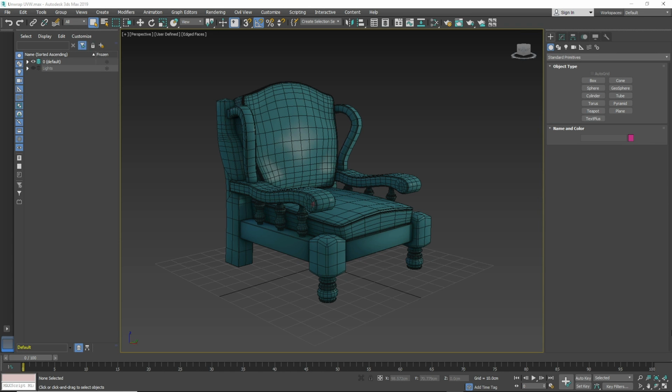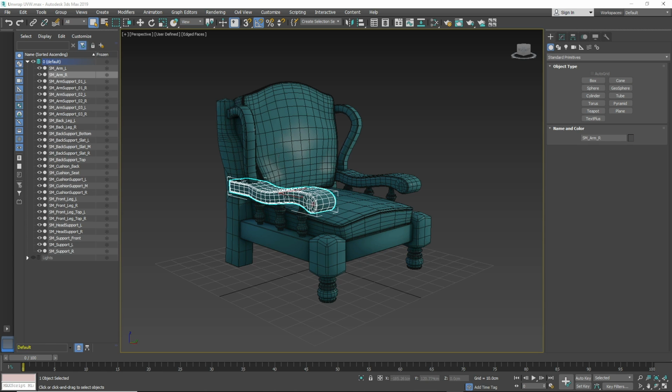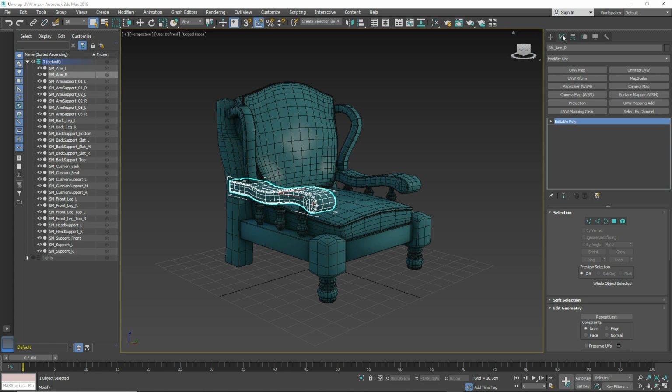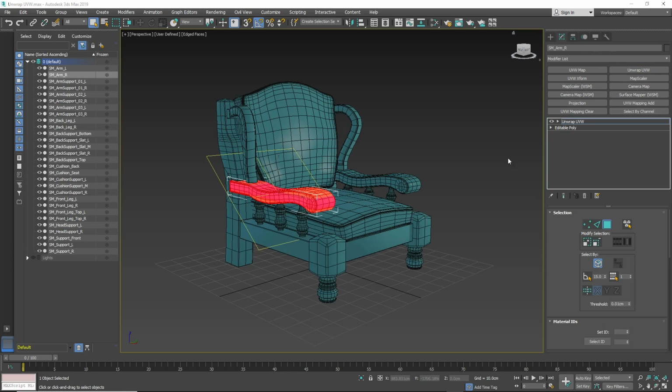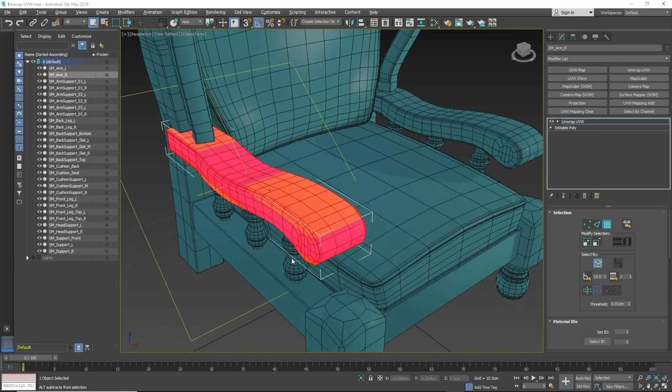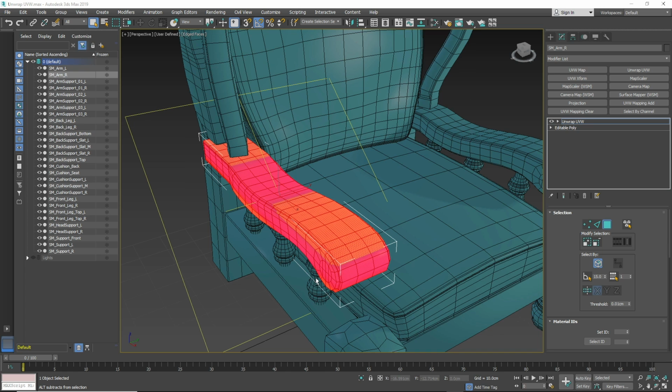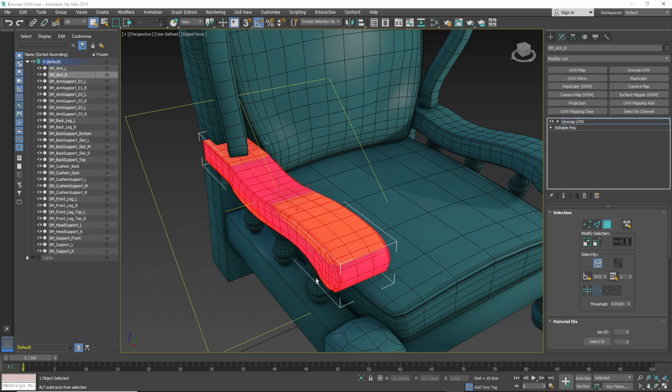Before we run through an overview of the options found on the modifier though, we will first of all need to go ahead and apply it to a portion of our chair geometry. In this instance, the arm nearest the camera should do nicely. And so, let's select that, jump into the Modify tab, and then click to select the Unwrap UVW modifier button that we have. Or we can select it from the modifier list in order to apply it if we didn't